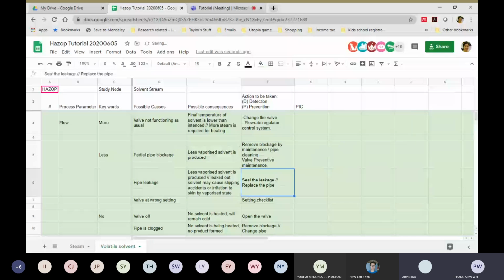What about backup pipes, miss? It's very difficult for us to have backup pipes, because how many backups do we want? If we know that over certain years the pipes may be blocked, then we set a regular maintenance, like every 3 years we will flush the pipes with certain solvent to dissolve all the blockage, the gunk, the residues of the chemicals in the pipe.